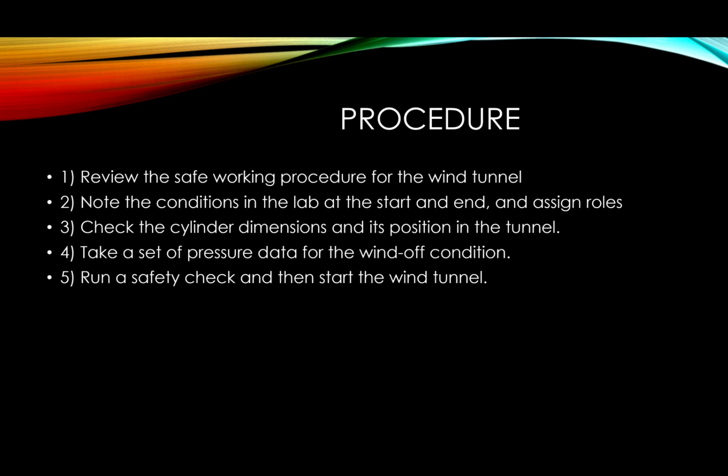Before collecting data for our lab, we went through the following startup procedure. First, we reviewed the safe working procedures for the wind tunnel. Next, we noted the ambient conditions in the lab and delegated roles. Next, we checked the cylinder dimensions and its position in the tunnel. Then we took a set of pressure data for the wind off condition, and last we ran a safety check and then started the wind tunnel.